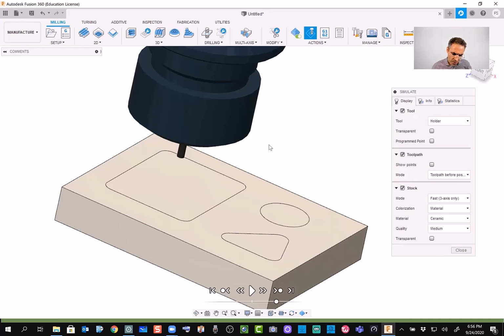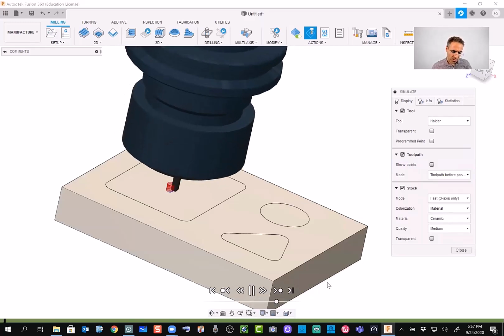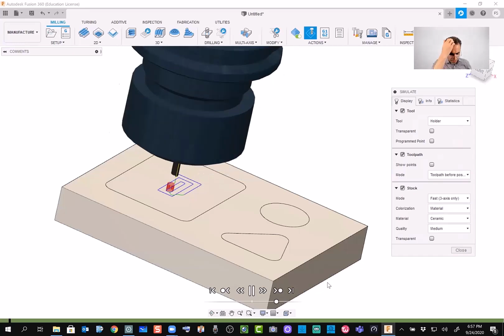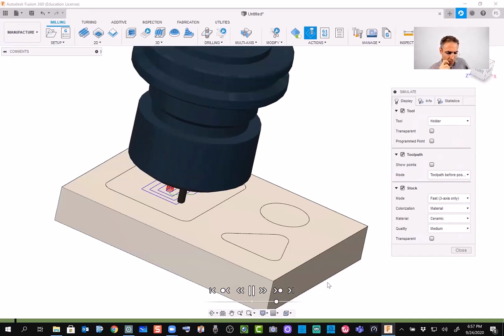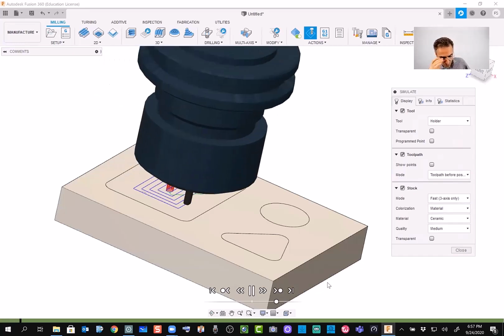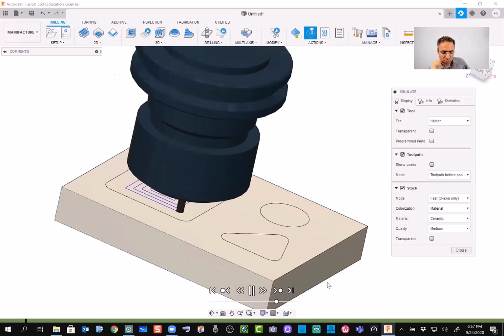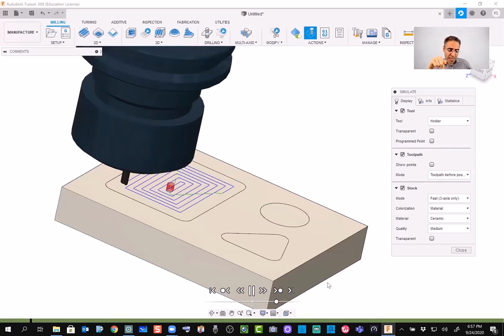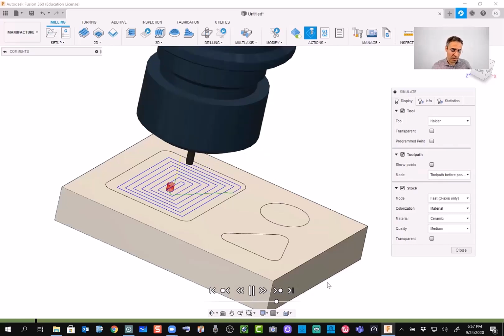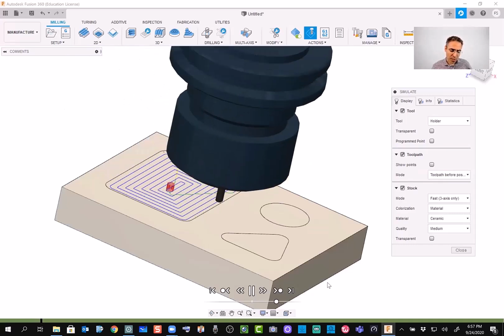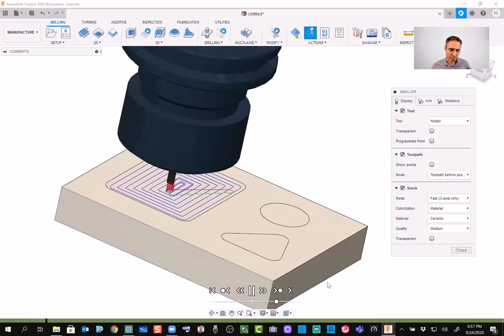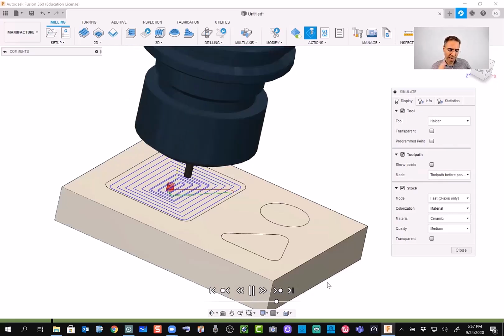If you are done with your visualization and you're happy with that, you see at the bottom this play button. Let's click on it and see what happens. I click on it. So it shows how these things are going to be cut. The tool path, in fact, shows me the tool path. The red one is when the tool is going in, all right? And then the blue is basically the actual tool path. So that was the first layer. And now the second layer.